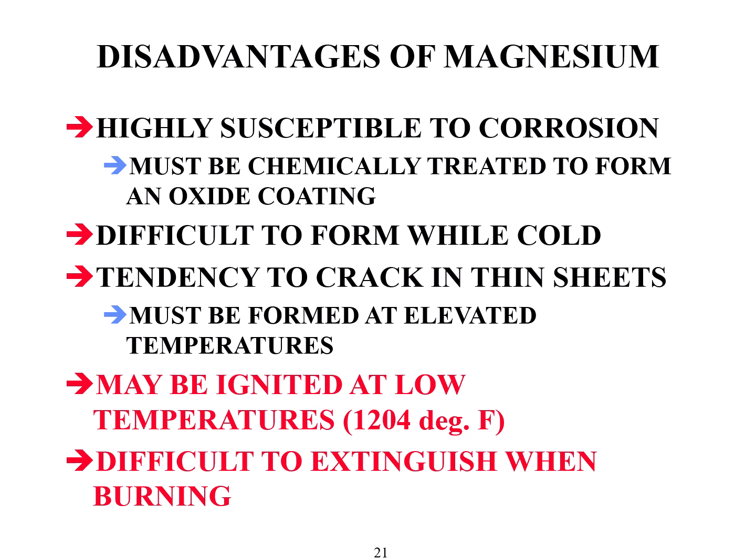There are certainly great properties. Here are some of the disadvantages. Magnesium is at the top of the electrochemical series of metals. Therefore, it will corrode. It will be anodic with exposure to any other metal. In a fist fight, magnesium is going to lose to every metal on the list. Magnesium is also so hard and rigid when blended with aluminum that it's very hard to form at room temperature. It'll crack rather than form.